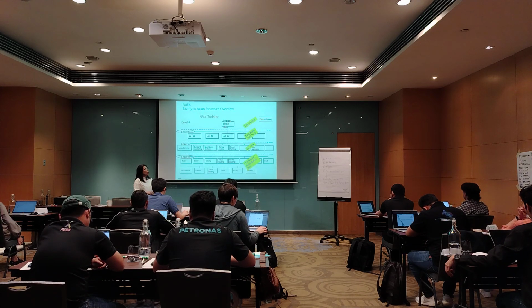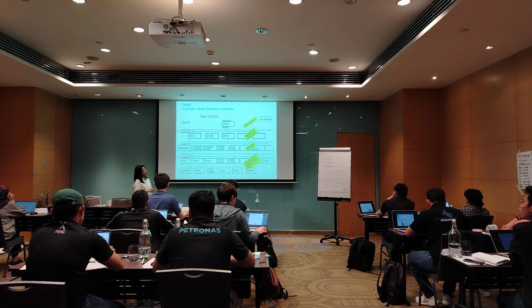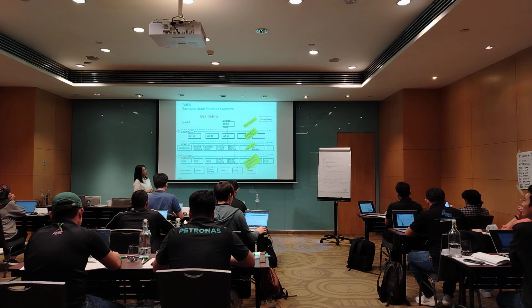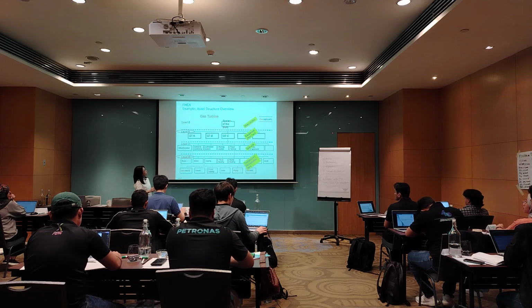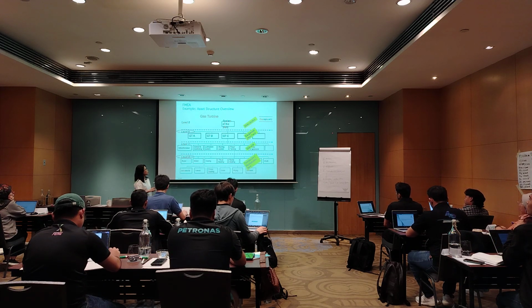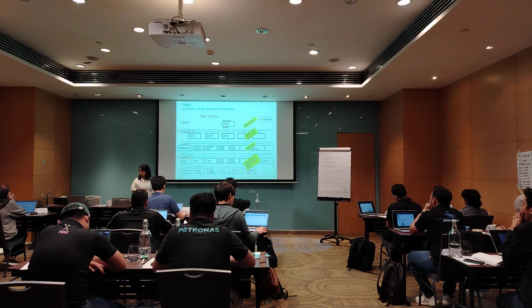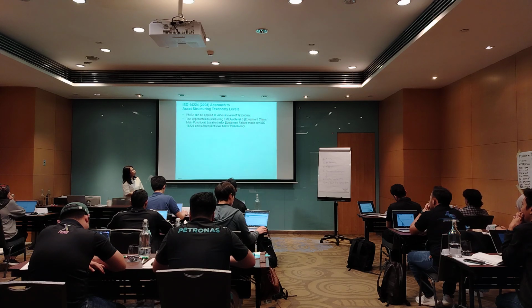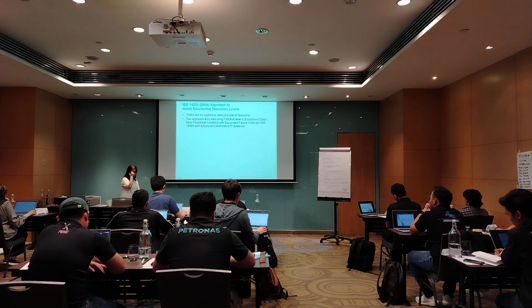I go back to here again. Why do we need to go back to here? Because inside this FMEA, should I start from here? From here? From here or from here? Which level should I start? 6. Yes, we should start at level 6. Why level 6? Equipment level. Should I start at system of the plant? No, right? It's too high level. Okay, then 6 onwards we should start, but not at the component level. All right. So this FMEA can be applied at various levels. So what I'm trying to tell you is it's level 6. It's an equipment level, equipment class level.